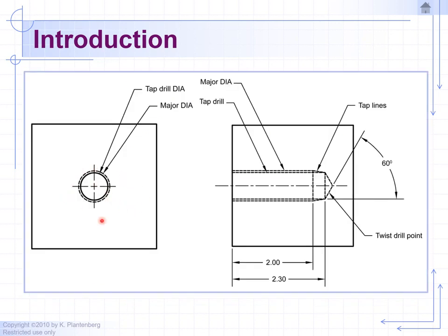And for a tapped hole, here we have a block with a hole that's tapped, so it has threads. The dashed lines represent the major diameter, and the solid circle represents the minor diameter. When we do a side view of this tapped hole, the simplified version is to do a double dash line to represent the major and minor diameter of the threads of the tapped hole.